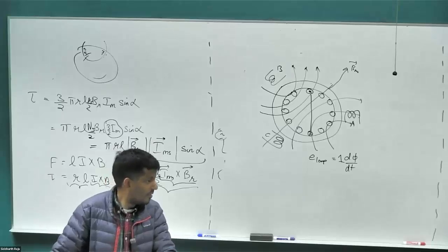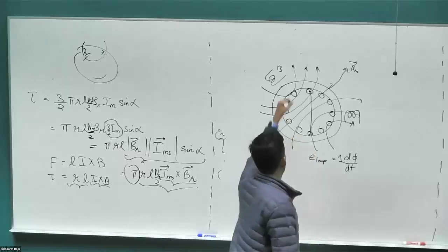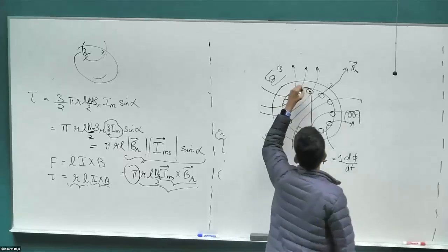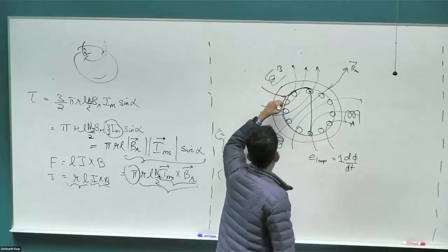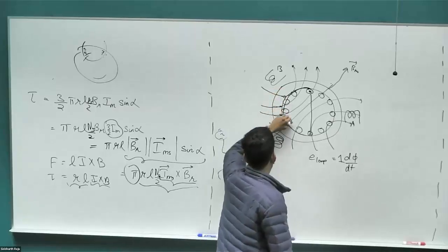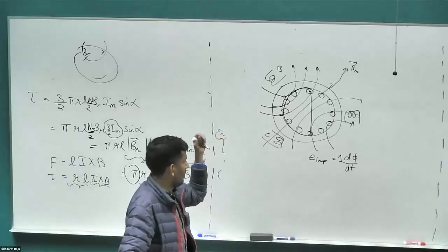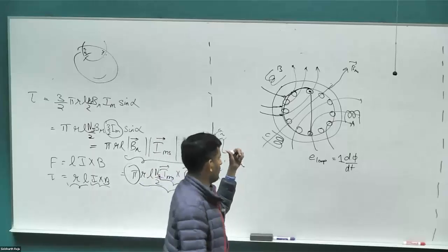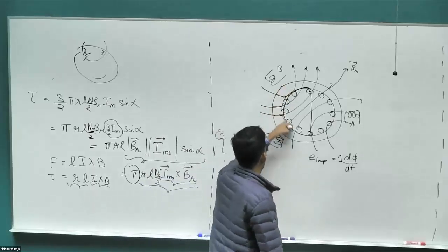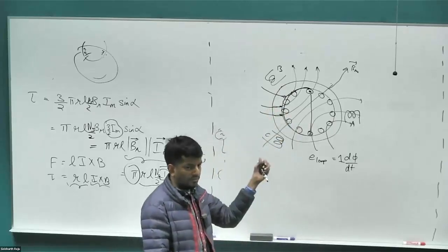Flux on the surface. Perfect. Which surface? That one. This part? Yeah. Perfect. So we choose the semicircle. We know at every point what the B field in the air gap is. And since this is iron, we already said when you have two iron interfaces with infinite permeability in the theoretical case, the B fields will always terminate perpendicular to the surface. So the B dot ds term is simply saying what the B field at every single point would be and multiplying by the incremental surface area and adding all of them up together.